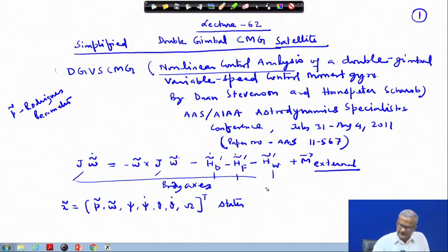Use the quaternions as we developed during the first 15 lectures. In your assignment the Rodriguez parameters have appeared, so the same equation goes here in this place. Those quaternions can be converted to the Rodriguez parameters, or you can directly convert the Euler angles to this, and thereafter you can use this equation to propagate the system states.